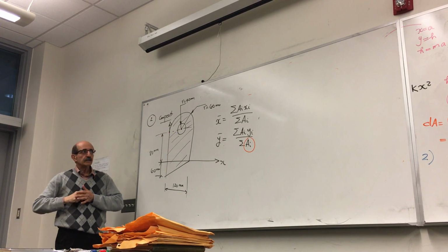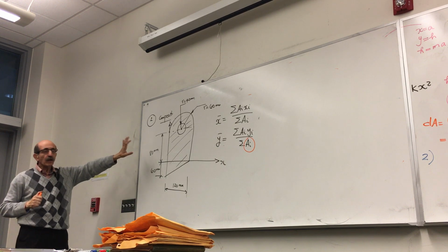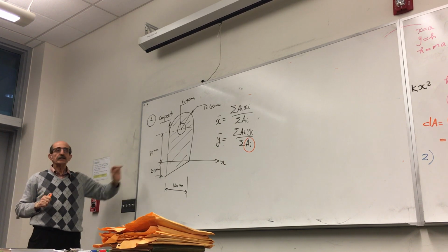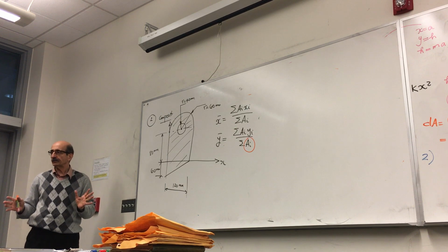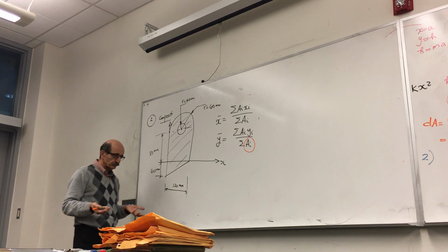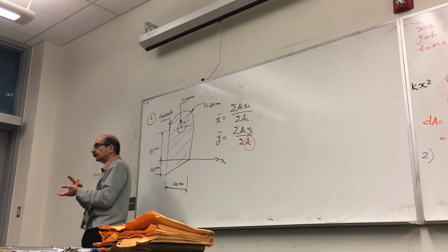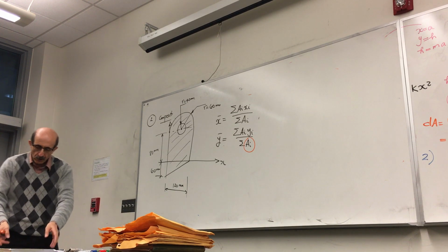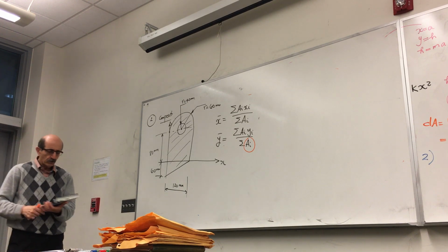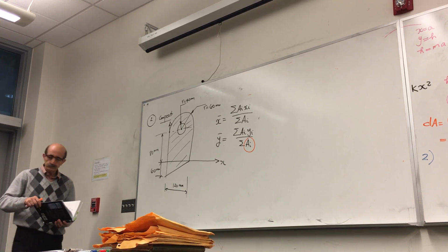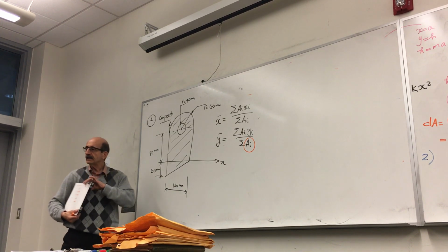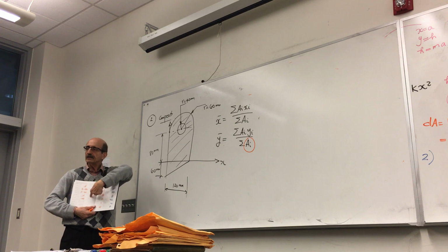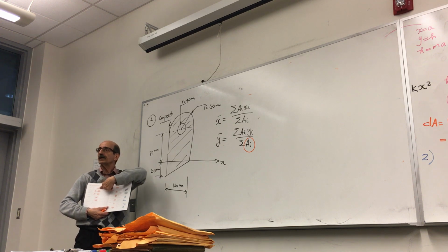You would subdivide this shape into simple geometric shapes. What I mean by simple geometric shapes, things like a rectangle, a triangle, a circle, half a circle, a quarter of a circle. In your book, for all those simple shapes, you're given a table that tabulates the centroid of each of those shapes.